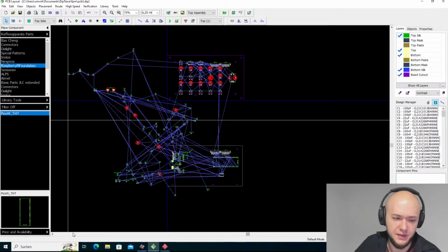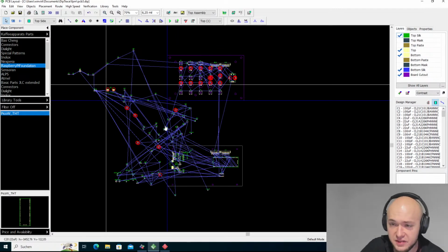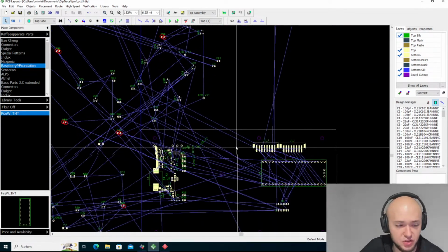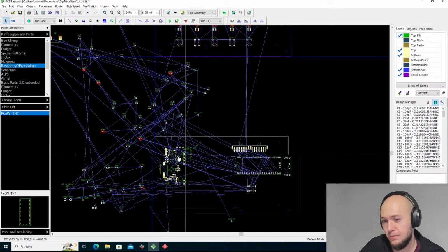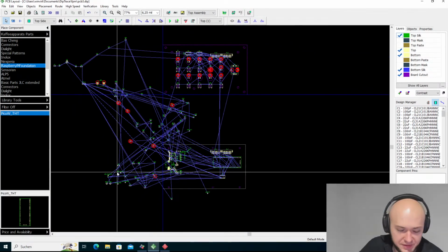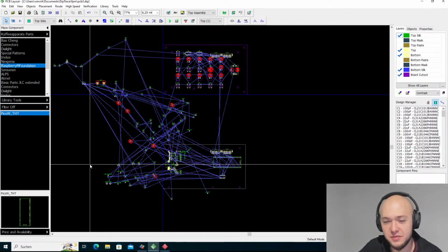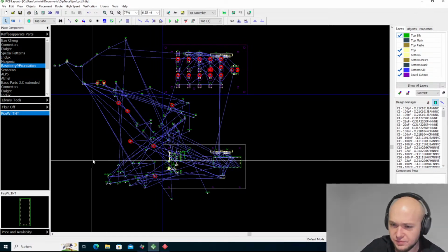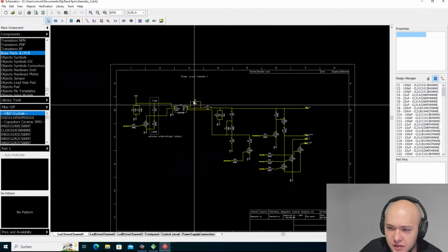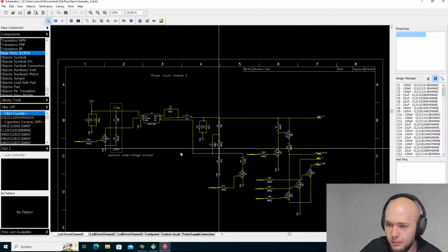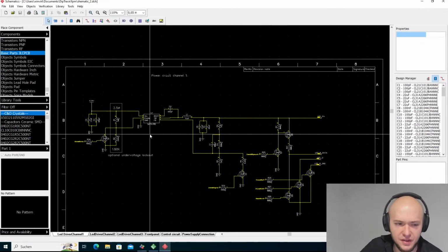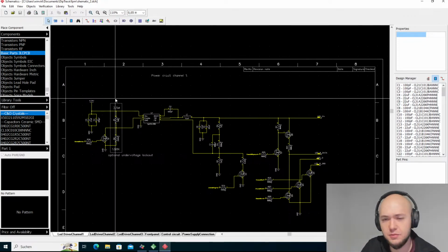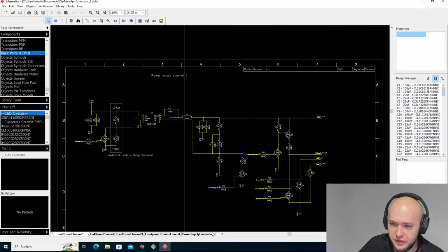Okay, what we did is we've started laying out the power supply section, but we don't want to do it 3 times. So I say we do it only 2 times, and we refactor the whole schematic again. Yes, but it's only a short refactor. We're going to use Diptrace hierarchies to copy the schematic 3 times. And with that hierarchy system we can also copy the design later more easily. So we're going to do this.